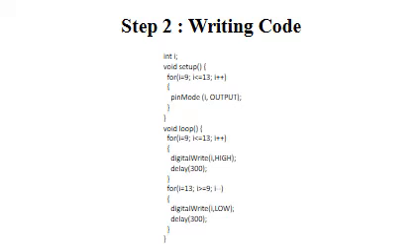The digitalWrite command is used for writing the status of the digital pin that is assigned to the digitalWrite command, and it must be an output pin so that it can transfer data to other components like LEDs, motors, actuators, and use them as per your needs and requirements.